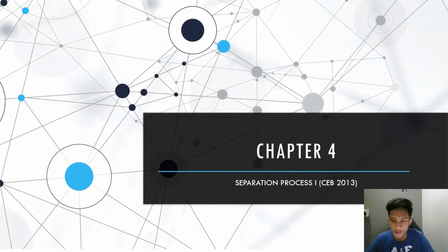Hi, I am Azrizan. I am going to explain chapter 4 of this project, which is the separation process 1 part. The objective of this chapter is to design a distillation column for a methanol purification unit, and also to determine how many theoretical stages are needed in that distillation column, which needs to be operated at the optimum reflux ratio. In order to get the number of theoretical stages needed, we need to draw a graph using the McCabe-Thiele method.